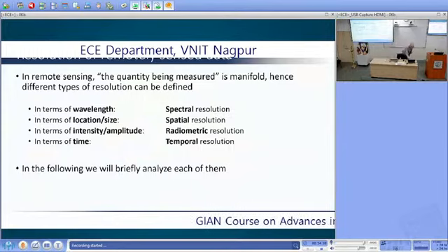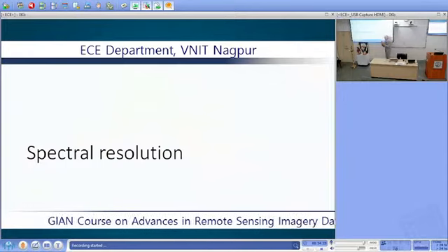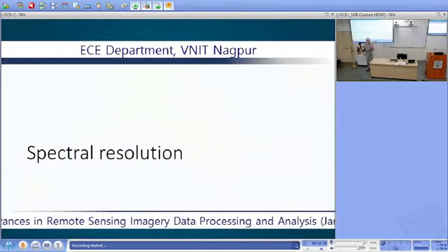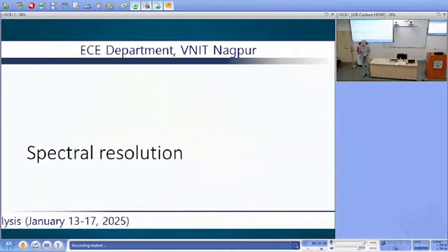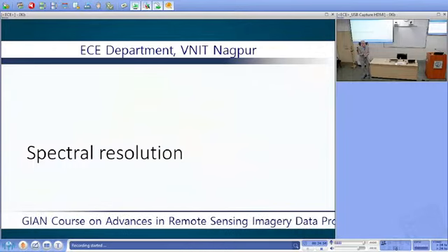One very important is spectral resolution. I already mentioned that. Depending on how fine are the intervals that you define when you decide how to break down the incoming radiation, that defines a resolution. Because the smaller the interval, the smaller the change in the reflectance curve that I can perceive using that sampling of data. And that's where the difference between multispectral and hyperspectral lies.